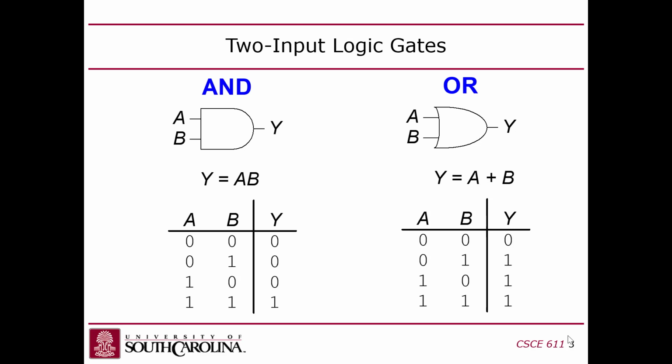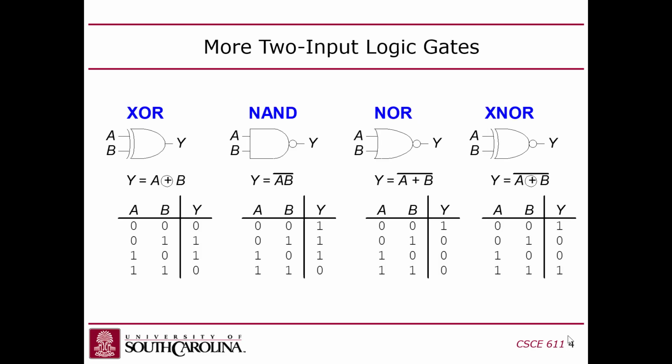There has to be at least 1 zero in there in order to build this gate out of CMOS logic. So if you need an AND gate in a real chip, you just use a NAND gate followed by an inverter. But anyway, okay. Then there's other kinds of gates. You guys probably remember XOR, NAND, NOR, XNOR. These are different truth tables, different Boolean operations.